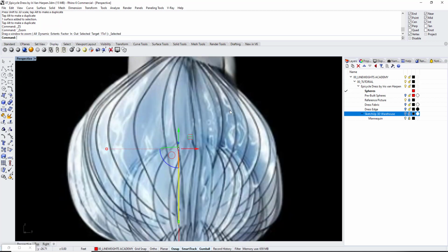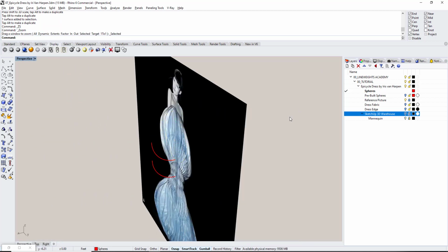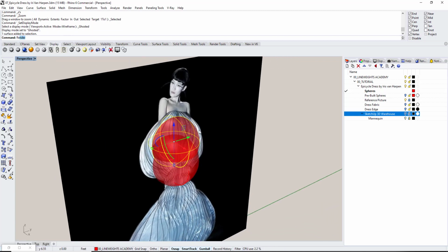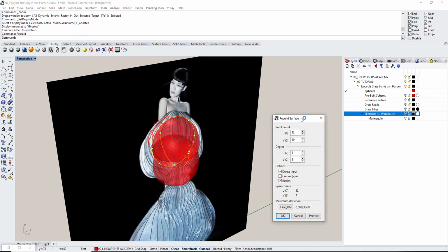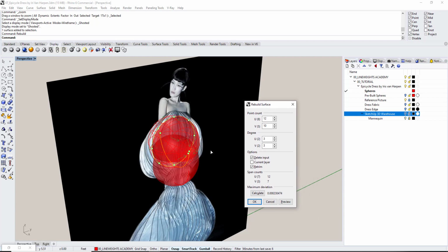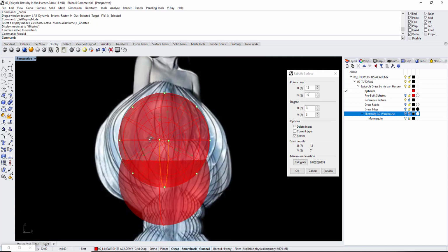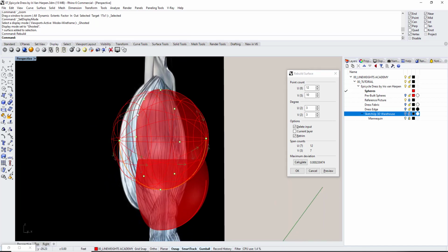So I would recommend, when you're dealing with a project like this and you need to modify any of these shapes, that you rebuild the shape. When you type rebuild, you get a couple of options, and one thing to realize, especially when working with spheres, is how spheres are built in Rhino. They work almost across poles. So here's a pole and here's a pole.